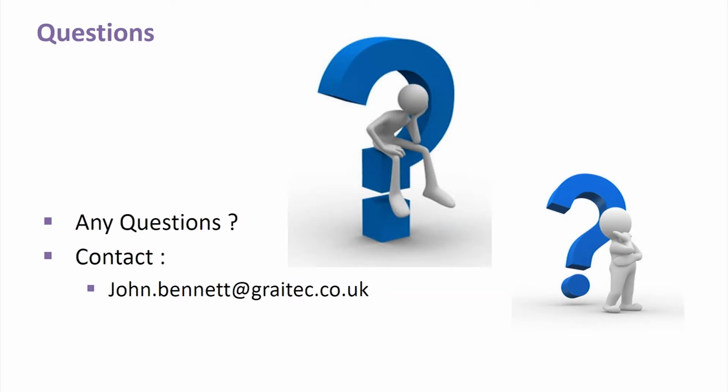Depends what you want to do with it. You can use the export import workflow. I think you need to be careful how you model the steel in Plant itself. I found some problems with that where people have not modeled it correctly, with the correct positions, etc., and it doesn't transfer properly from what I've seen. Might be slightly better in 18. I know they had a couple of alignment issues in the USA for positional issues, which is why we probably did this workflow.